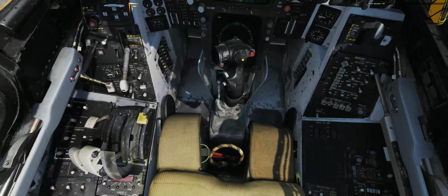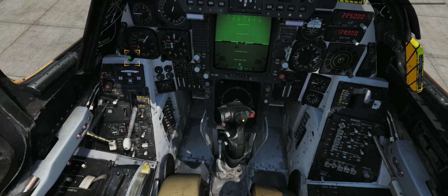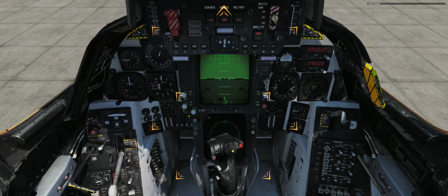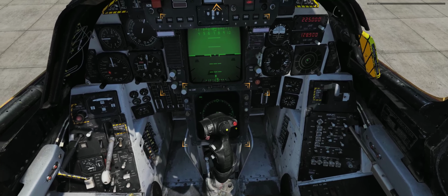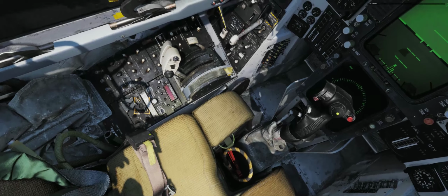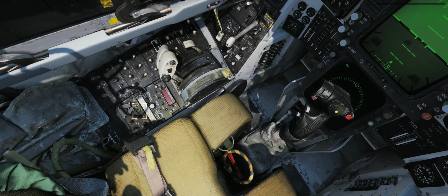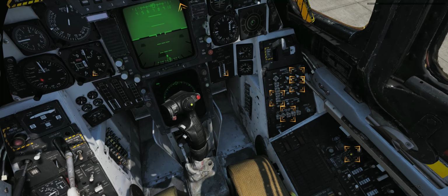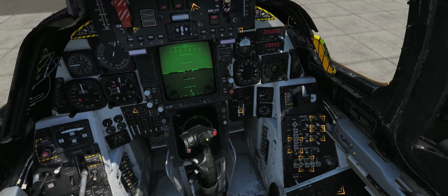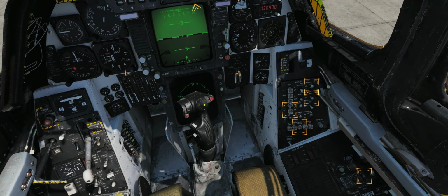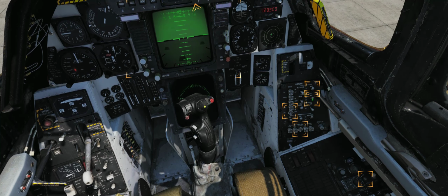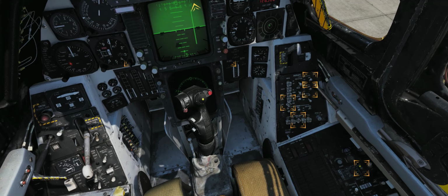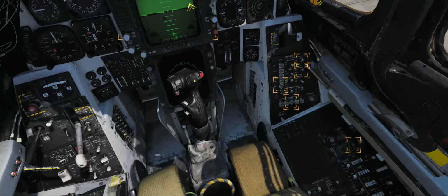Run radar altimeter bit by depressing the knob. Check that displays are set as needed. Run TACAN bit. Run ARA 63 bit. Set altimeter reference pressure and reset mode.